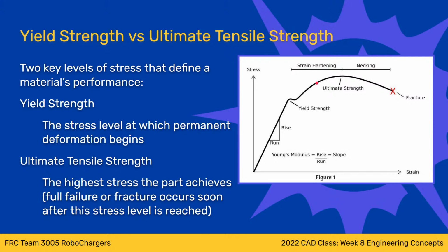Well, what actually happens, generally speaking, is that this point basically becomes the new yield strength of the material. And then when I let go, the material essentially just follows this new straight line downwards, and essentially I have created a different yield strength for the material because I deformed it.